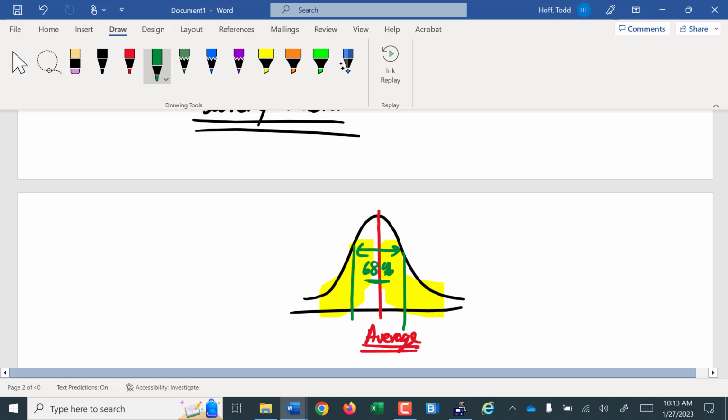Now, that standard deviation for a 20,000 pound average could be 300 or 400 pounds. So 68% of your ropes are going to be between 20,000 and 21,000 if you have that 20,500 rating. But it's still possible to go outside that range. 95% will fall within 2 standard deviations. So there's a portion that would be further out. If that's a 400 or 500 pound standard deviation, it could be 1,000 pounds less or 1,000 pounds more.